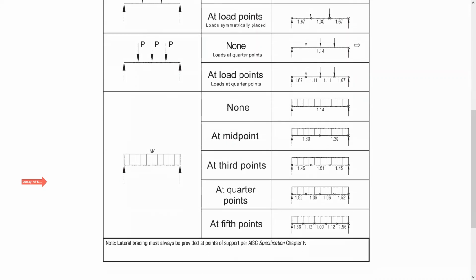It's a simply supported beam, and there is no bracing along the span length. We just have bracing at this end and the other end, so here it's none because we have nothing here. So Cb is going to be 1.14 without doing any calculations, because there is an equation, and I did introduce this equation to you last class. So we're going to use this value.